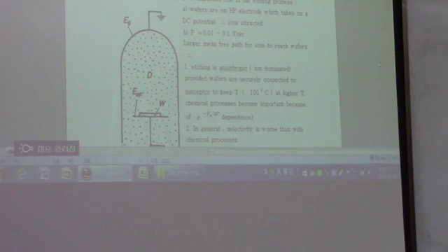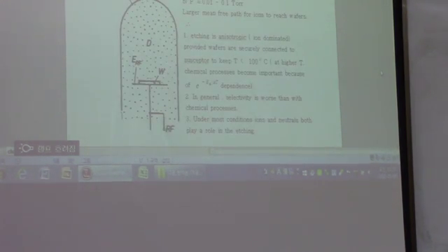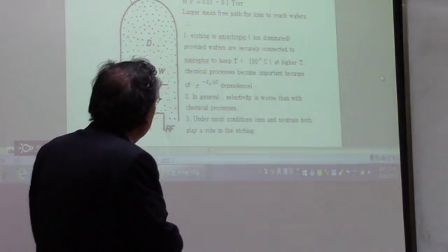Is the most popular dry etching system used in the industry. Okay, in these systems, ions play an important role in the etching process. In the planar type and the barrel type, we neutralize the ions and the fragmentized fluorine atom itself plays an important role in the chemical reaction, right?